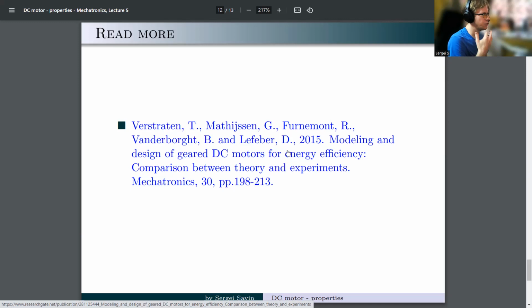Whereas the classical approach in control theory is to consider a system with arbitrarily many states, here we have specifically a second order system, for which a lot of this becomes much cleaner and simpler. This simplifies the topic, but it also imposes on us the necessity to understand exactly what's going on. Not just that in principle you can place poles, but what exactly you're placing, what exactly you're making. This is what we are going to spend time on in the next two lectures.